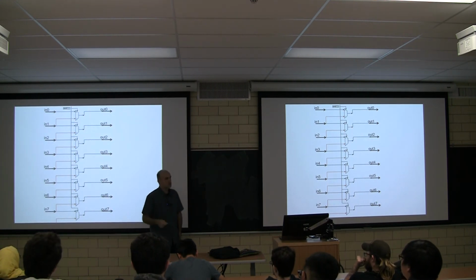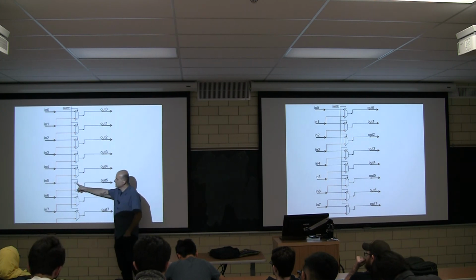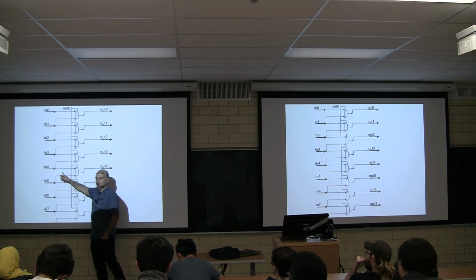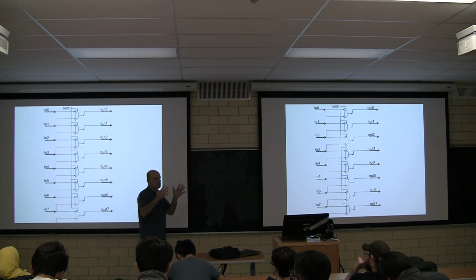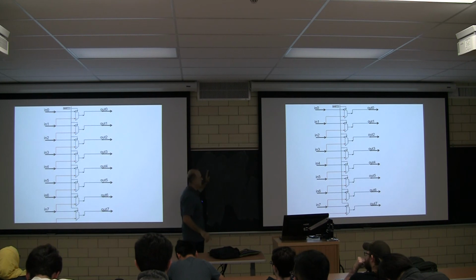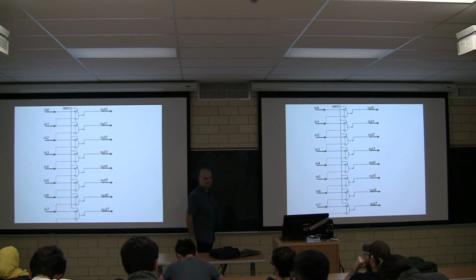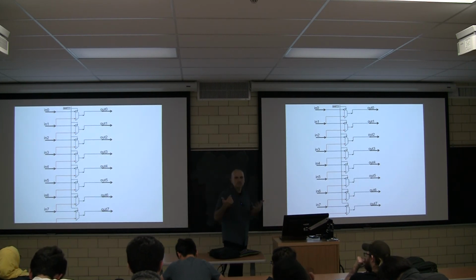However, there's a control signal that controls all these multiplexers. If you make that 1, notice that in 5 becomes out 4. So we're shifting right. If you were to view this on a board, bit 5 goes to bit 4. Fair enough? So this supports shifting by 1.